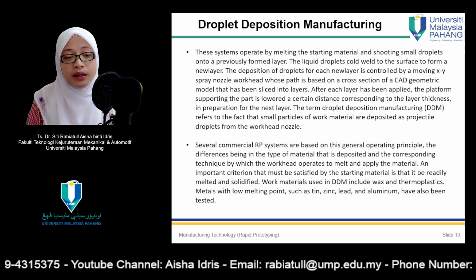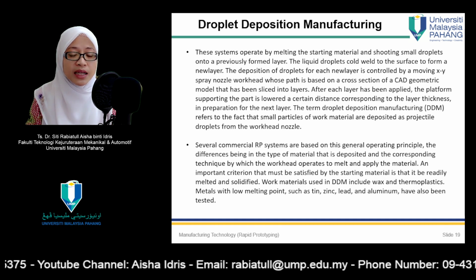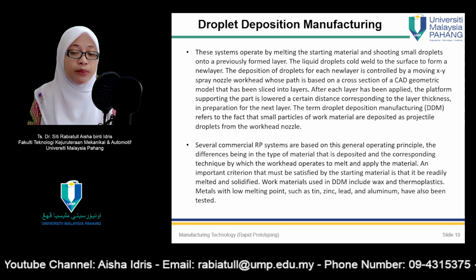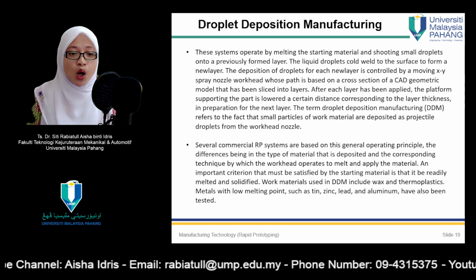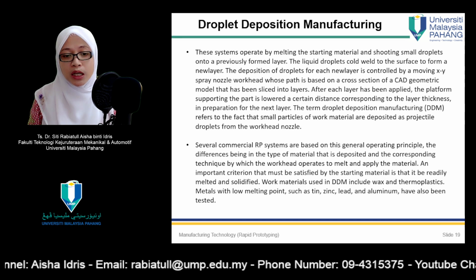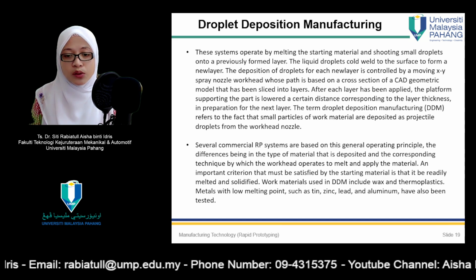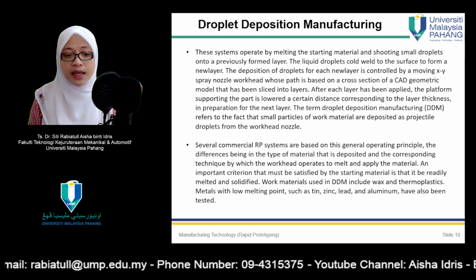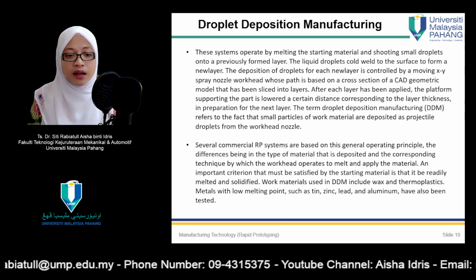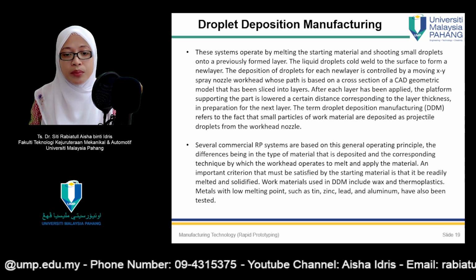An important criterion that must be satisfied by the starting material is that it be readily melted and solidified. Work materials used in DDM include wax and thermoplastics. Metals with low melting points such as zinc, tin, lead, and aluminum have also been tested.